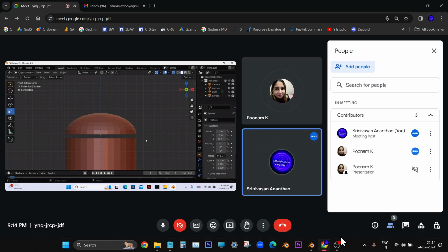Right now, we have to add. We have to extrude. No. So first, select the cylindrical post. We can do the extrusion for the cylindrical post. Below one post. Yeah, that one. Now press dot, frame selection. The entire object we should be able to see. Only then we can add.